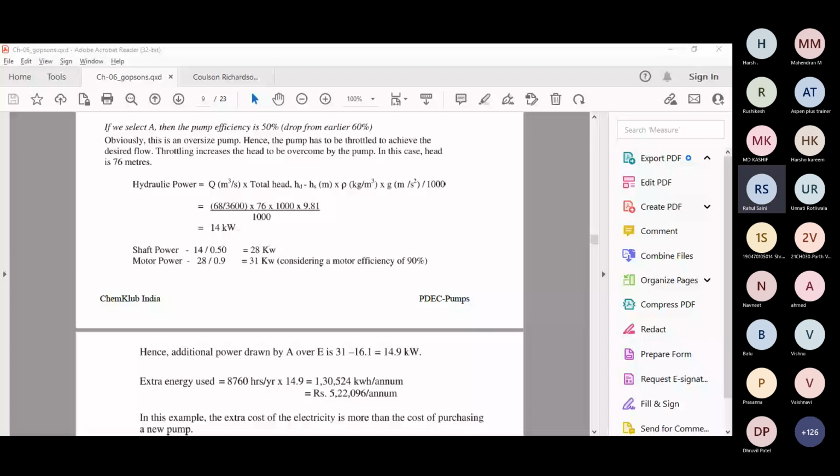Okay, you are saying that we can somewhere provide a three-way valve kind of solution. Correct. We can provide a control loop over there and provide a three-way valve according to the temperature. Yes, exactly. Three-way valve is the best option. But this is applicable for heating systems and cooling systems only.